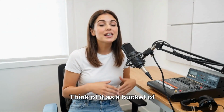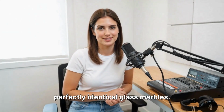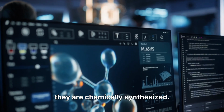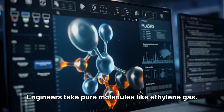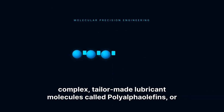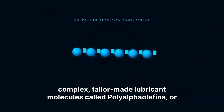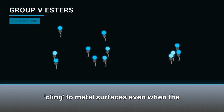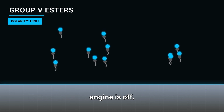Think of it as a bucket of perfectly identical glass marbles. Synthetic base oils are not simply refined, they are chemically synthesized. Engineers take pure molecules like ethylene gas. They chemically bond them together to build complex tailor-made lubricant molecules called polyalpha olefins, or PAOs. Then we have Group V esters. These are highly polar, meaning they chemically cling to metal surfaces even when the engine is off.